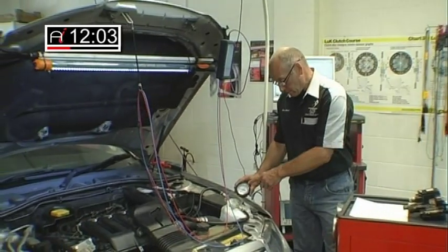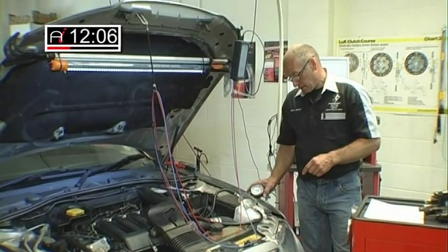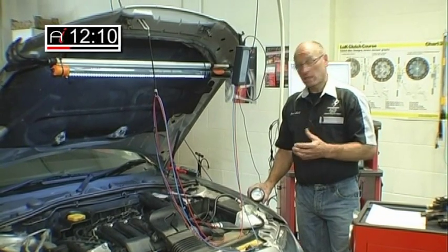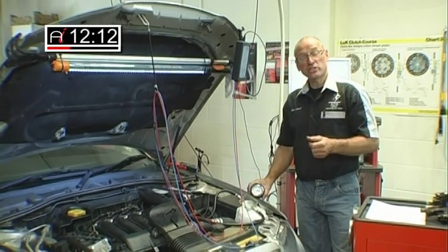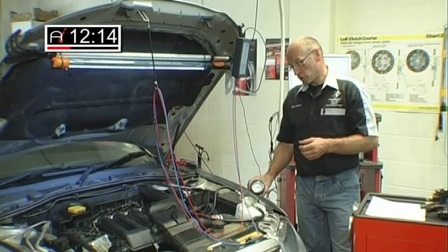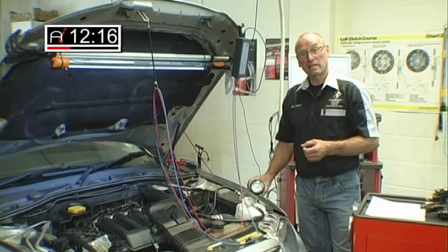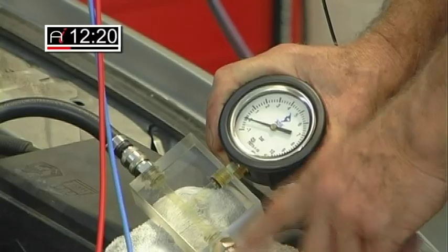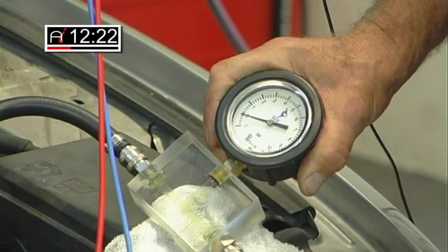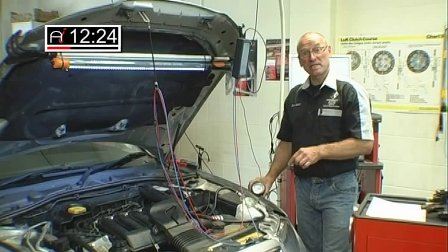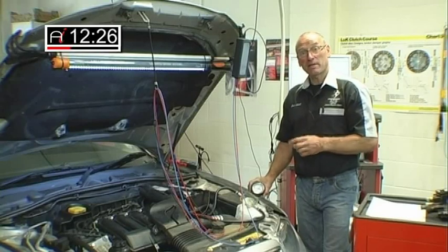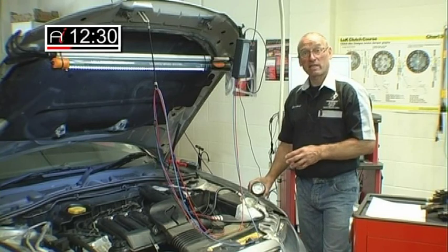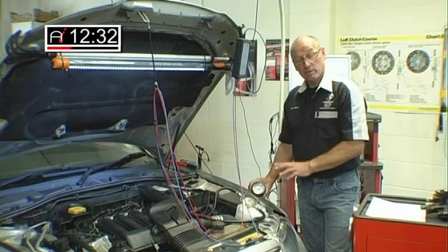So the first thing we need to do now is simply, in fact, this particular system will prime simply by turning the key on and will provide the right pressure. We don't actually need to run the vehicle, although we do have the ability with this gauge. This gauge has self-sealing couplings so that we can extend these hoses into the vehicle if need be and drive the vehicle on the road, actually monitoring real-time hydraulic events. In our case, for the moment, we're doing it in the workshop.